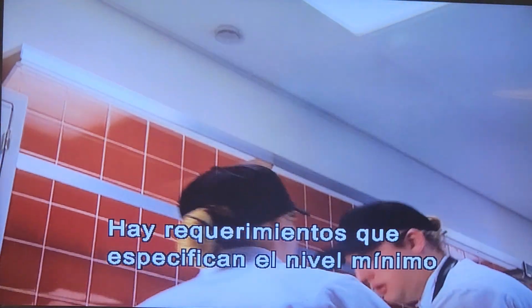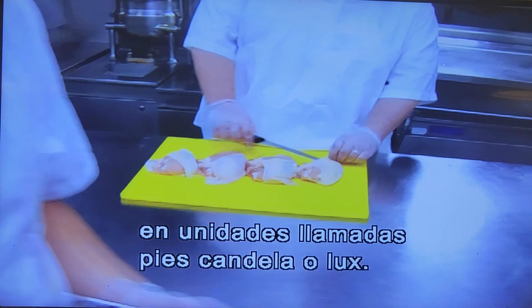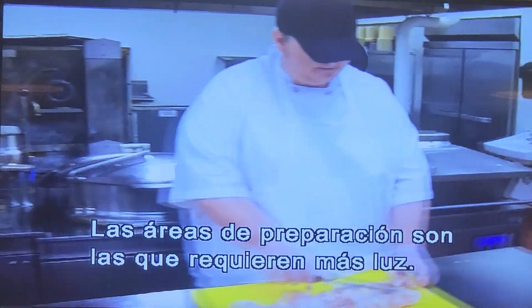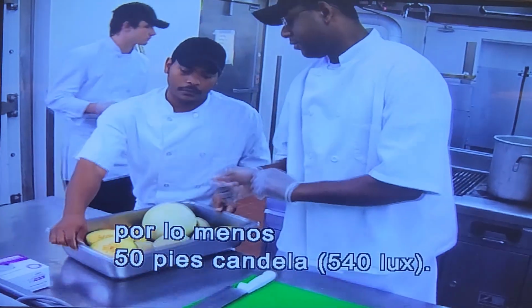There are requirements that specify the minimum level of light necessary in each area of your operation. Lighting requirements are usually measured in units called foot candles, or lux. Prep areas require the most light. Here, lighting must be at least 50 foot candles, 540 lux.